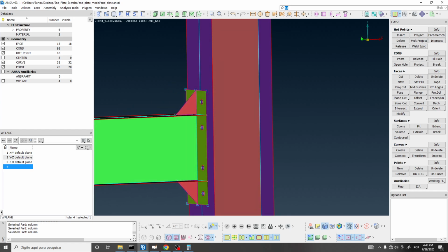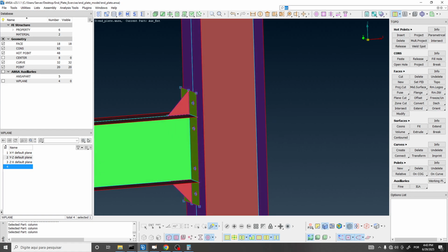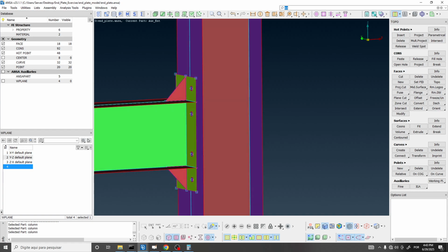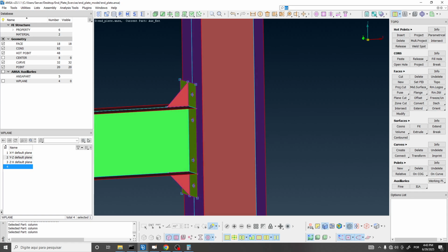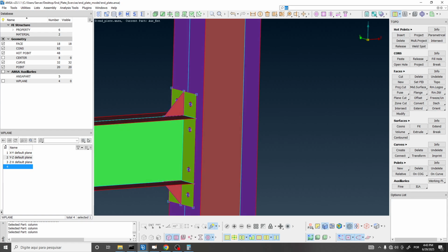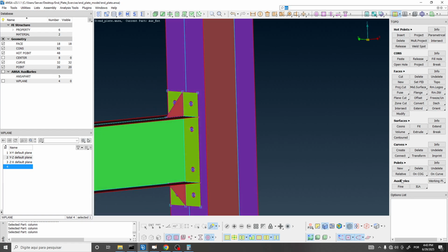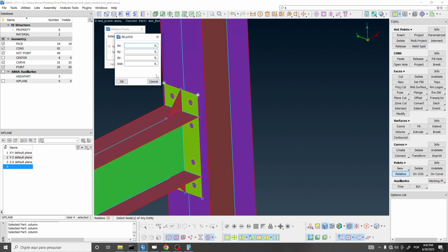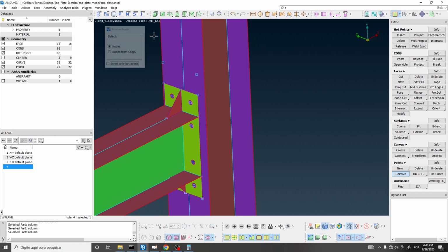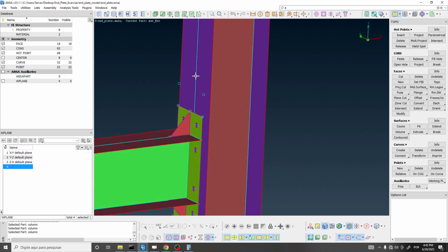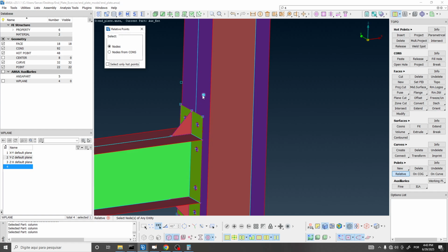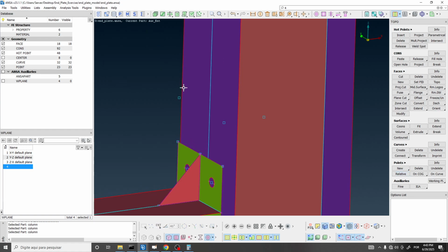Okay, so we're going to learn about a new tool here that is very important. Let me think here how we can do this in the best manner. Okay. I'm going to use again the relative tool for points. Select these 2 points, middle mouse button, positive z direction, 100 distance, click on OK. Now I'm going to use again the relative tool, select this point, middle mouse button, and positive x direction, and a distance equals 100. Just follow what I'm doing. You're going to understand what I'm going to do here.